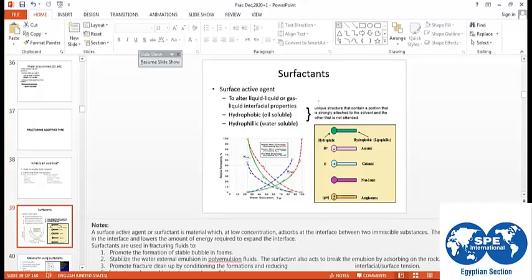Also, selecting the concentration of the breaker should be done on actual conditions. You have a fluid bath with temperature equal to your reservoir temperature, and try different concentrations of the breaker on a cross-linked gel sample and measure the time of breaking.